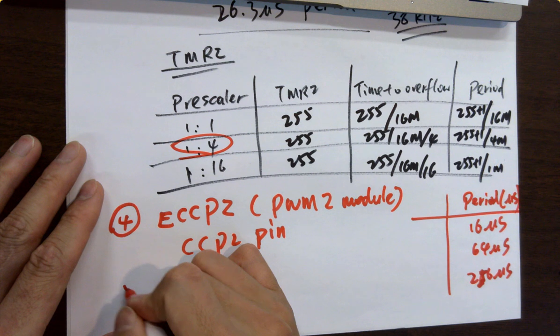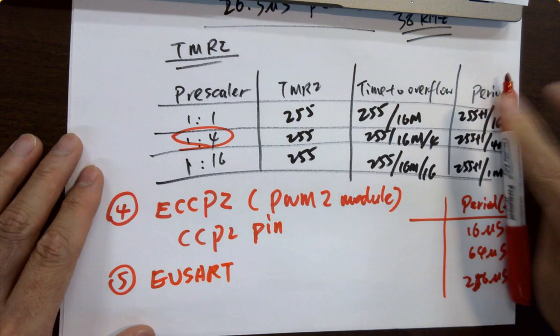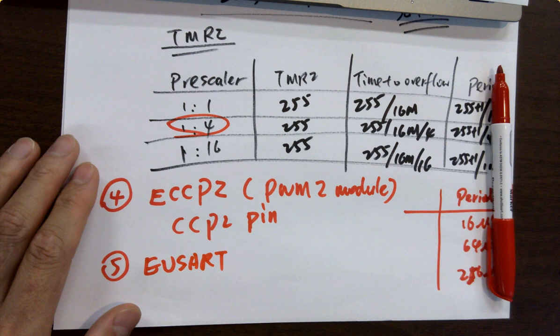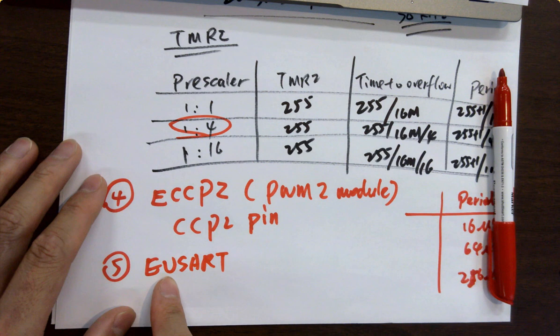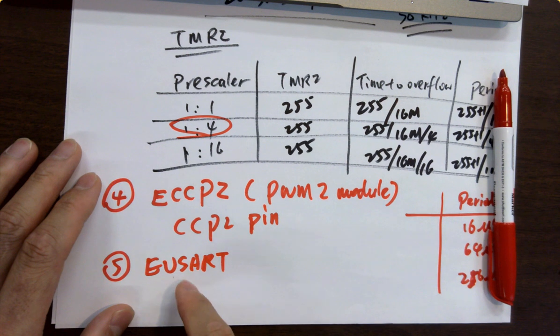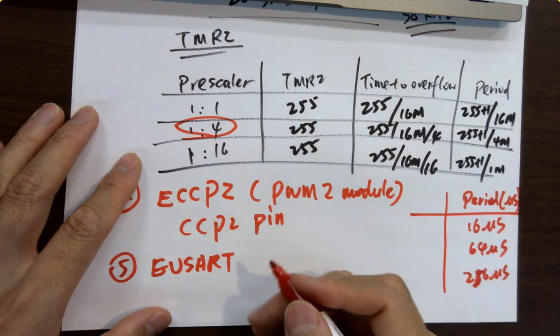For the UART, EUSART, people are asking what's the difference between EUSART and UART. So the Microchip digital engineers added some features to the UART pin, but UART is just UART. You put it down to 0 as a start bit, and you output the data, and then you put it up. That's the same protocol. It's not changing. It's just UART.